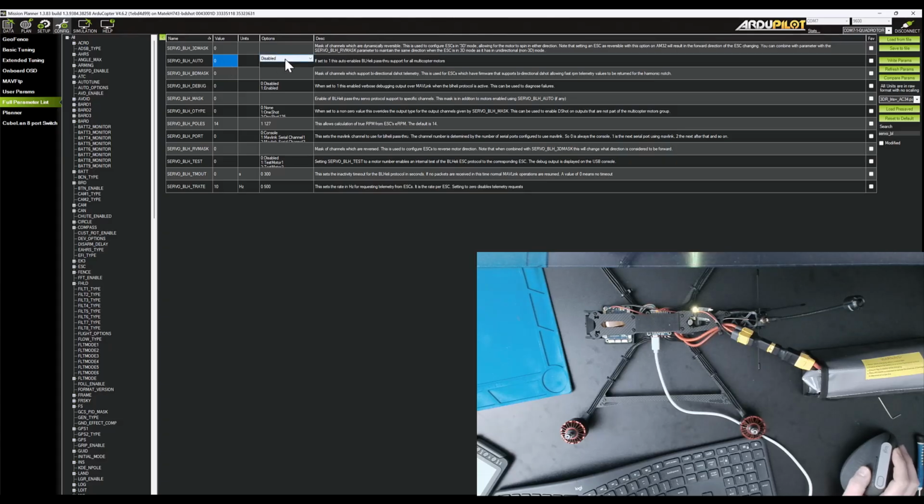It means that it does not allow us to change motor settings using the standard way that we are doing for BLHeli. Then we open a browser, open ESC configurator, for example, am32.kiwi portal, and set up motor direction through there. But it's possible to enable this parameter and write params. Click OK, OK, and obviously a reboot is required.